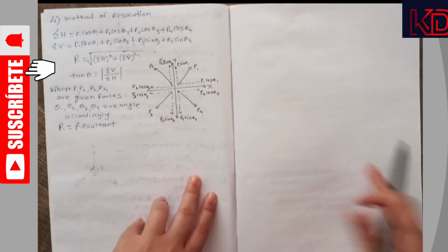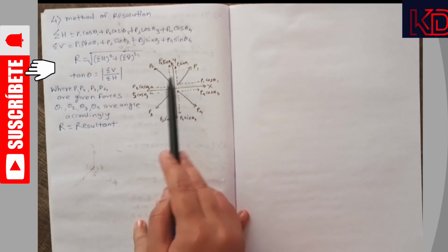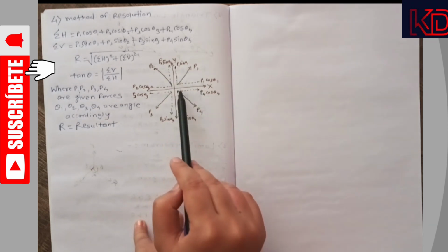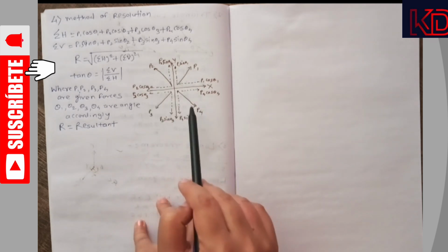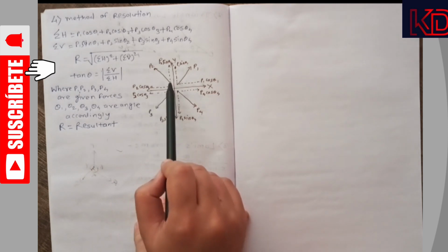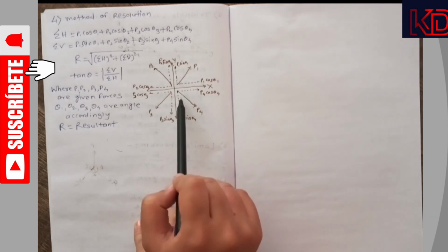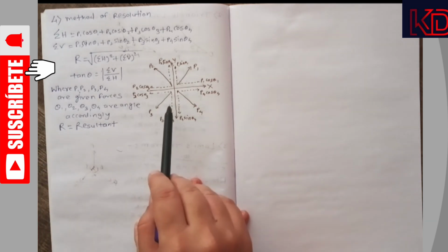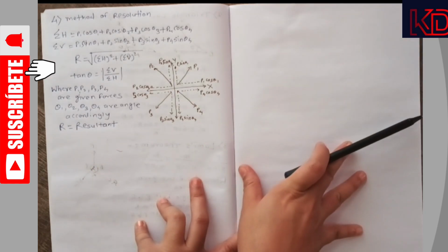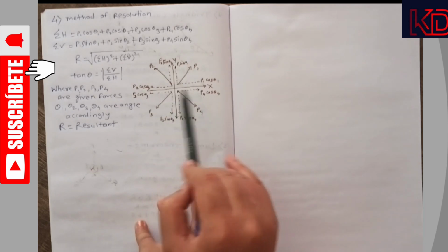Now the last but not the least, the method of resolution. I have drawn this diagram, so try to understand it. I have drawn the x and y axes. Then P1, P2, P3, P4 are the respective forces acting on that particular particle. Then we have resolved these into sine theta and cos theta components, because the angles I have assumed as theta 1, theta 2, theta 3, theta 4 respectively. Then we have resolved them into parts, that is P1 cos theta 1, P2 cos theta 2, and likewise.